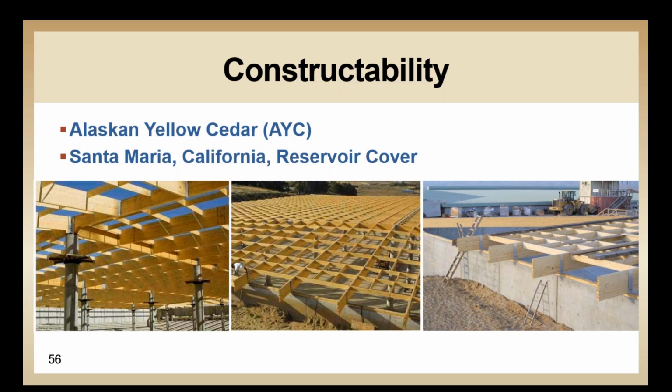From a construction standpoint, the glulam offered another benefit. There was a time savings associated with this. If the project had been constructed with open web trusses that used dimension lumber for the cords, the lead time to source materials in the size needed would have stretched into months. The glulam provided an environmentally friendly alternative, allowing the use of wood from smaller diameter trees to form the framing members, and the project was completed on time and $50,000 under budget.